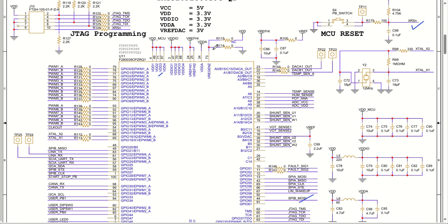Similar to that, this particular pin has been grounded so that the VDD pin will be taking power from VDDIO internally through an internal regulator, and we have the VDDA pin that is taking power from VDDA. These two power supplies are properly filtered through ferrite beads. We have reference requirements. The reference voltage is generated at 3 volt, and that is going to my analog ADC